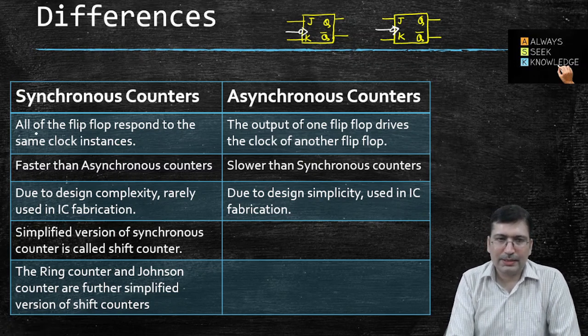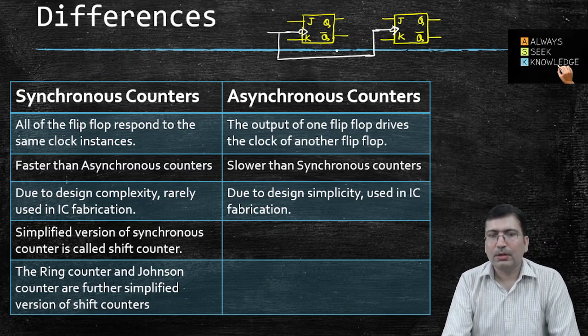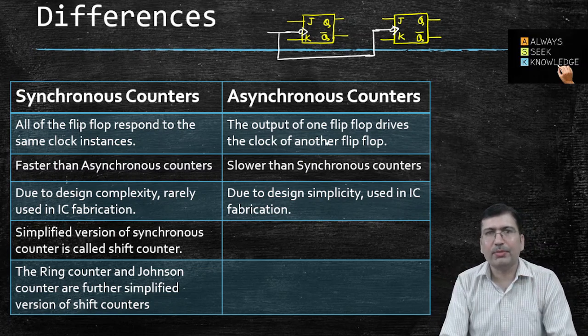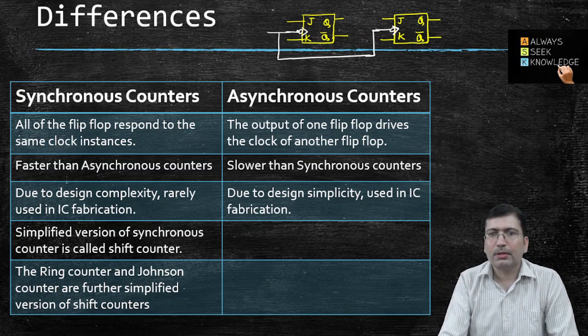As the statement says, all of the flip-flops respond to the same clock instance. So if we pass the same clock to all the flip-flops which we are going to use, so in case you connect this clock to this clock, then these two flip-flops will activate or deactivate at the same time, synchronously. So the circuit will behave synchronously.